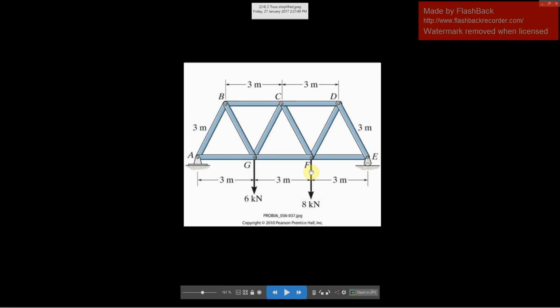This is an important first step. The location of all of these points, which I'm going to call nodes from now on, is important. That's basically what we're going to do: build these nodes and then join them up by beams. Knowing all these points in space is super important, and when you do your models for your own towers, knowing these points in space is going to be important for you.